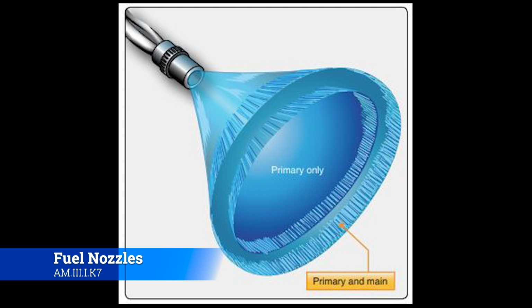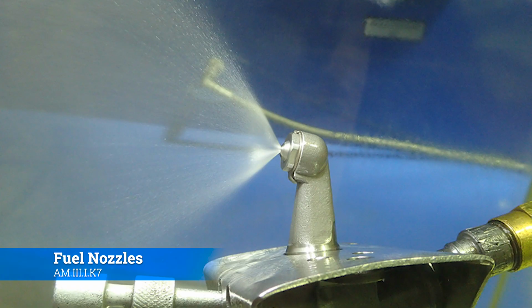So let's look at a simplex spray pattern, and you can start to see the difference. Okay, so this is a simplex spray nozzle. It's in the name. It's simple. You can see that it's shooting off a fan pattern of highly atomized fuel. Atomization is just a fancy way to say that it's a spray.